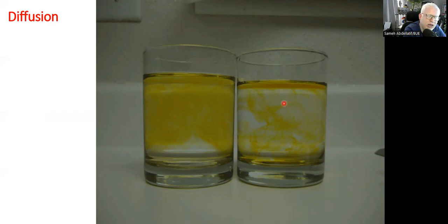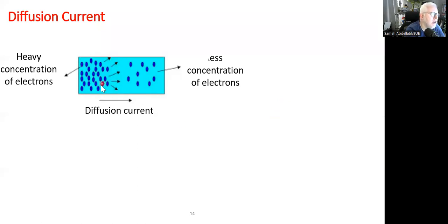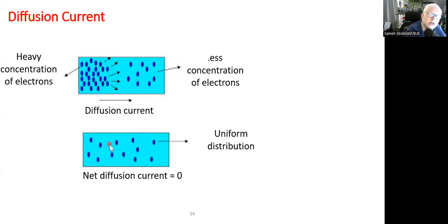A diffusion current is a very logical phenomenon whenever you have a variation in concentration between two sides of a material. Herein, the variation of concentration is in terms of electron or hole concentration. So when you have one side of a material with a higher concentration of electrons with respect to the other side of the material, then what we should expect is that current will start to move from the higher concentration region or side to the lower concentration side till we reach a homogeneous concentration across the material.